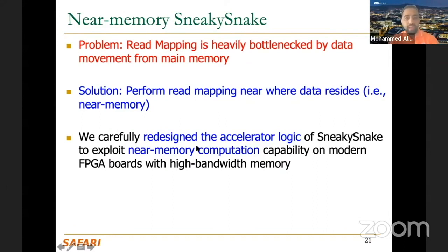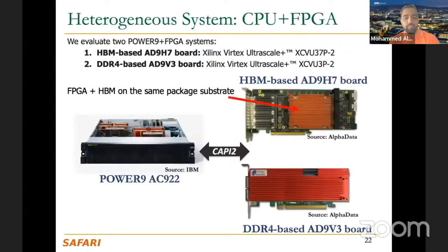So that is a capability or a nice feature provided by Xilinx in their recent boards, and this is the board number. So you can go with UltraScale boards. Most of them have this high bandwidth memory, or HBM, that is located next to the FPGA logic. So you have the memory chip located either in the same package or very next to it.